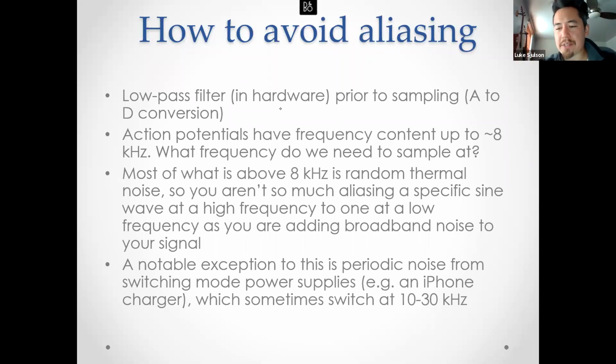And if you're doing electrophysiology in a mouse that's licking a spout, you want to be able to detect when the animal licks the spout. And this is actually not a trivial problem, because you can have a vibration detector, which works, and you can also have infrared light beams. But if you want to pack them close together and you want it to be very sensitive, then the best way to do it is to have it electrical and just pass current through the animal, right? You can pass such a small amount of current that the animal can't feel it, but that's the most sensitive way to detect a lick.